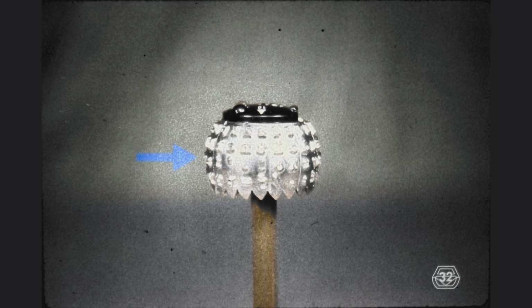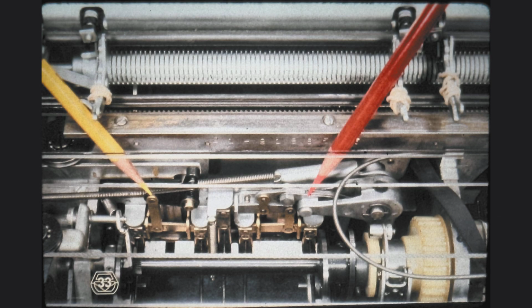We use the portions of the rotate mechanism called the positive 5 rotate mechanism and the negative 5 rotate mechanism. The mechanisms indicated here are used to perform character selection. They are part of the output section of the Selectric typewriter. The yellow pencil indicates a point in the tilt differential, and the red pencil indicates a point in the rotate differential.